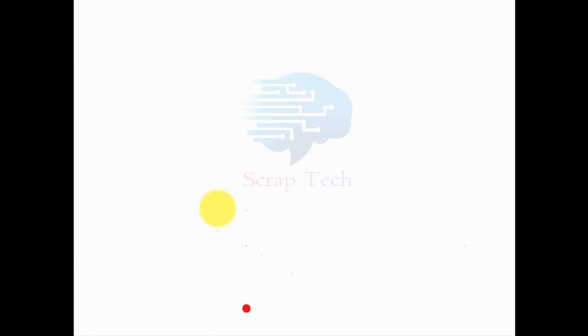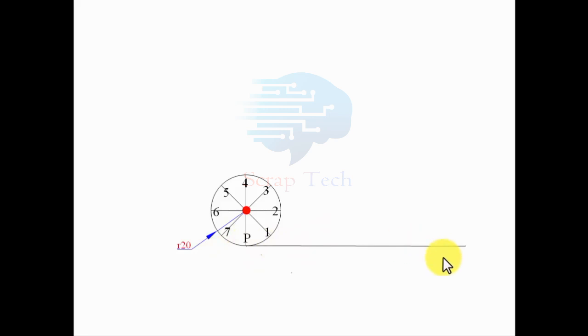So let's start the construction process. We have a point which represents the center of this circle, having a radius of 20 millimeters. Diameter has been given to us as 40, so the radius is 20. Now let's do 4 divisions of this circle. Let's make these 4 divisions 8 divisions, something like this. Now let's name each and every point. Starting from this point, we have this as 1, 2, 3, 4, 5, 6, 7, and let's say this one is P. Now we have to place a string, and right now we'll be placing a string in the form of a line somewhere along here, like this. This string has a length of 125.7, which in fact is equivalent to that of the circle circumference.